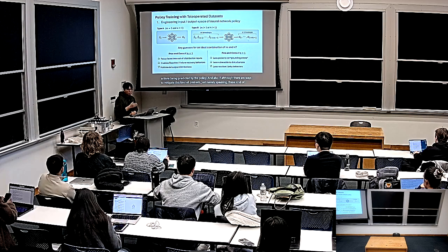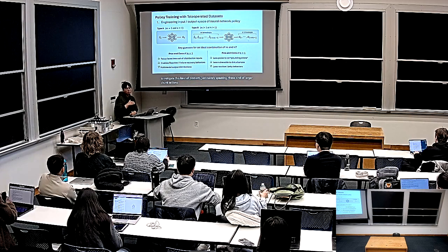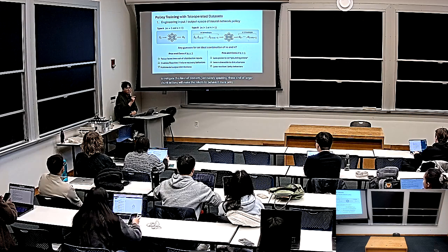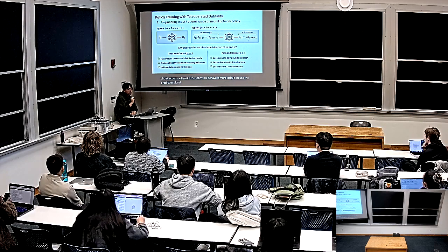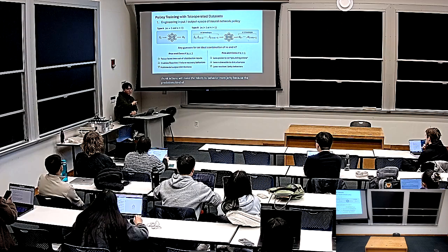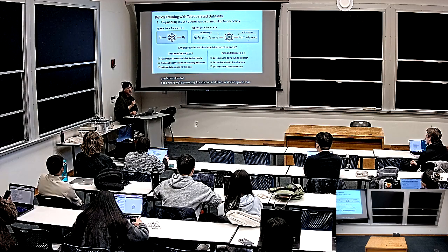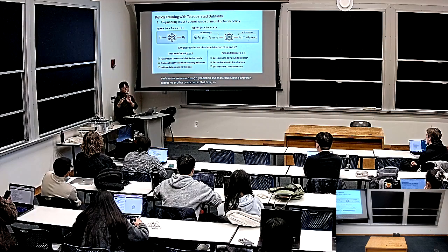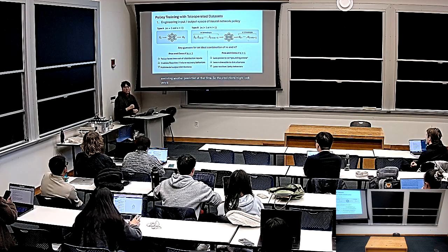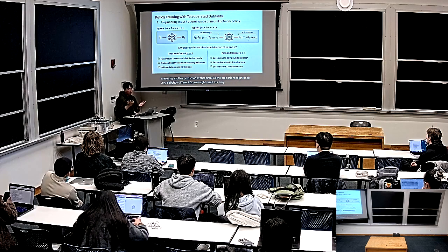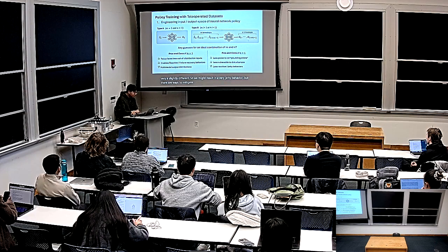And also, although there are ways to mitigate this problem, just naively speaking, these larger action chunks will make the robot behave a bit more jerky. We execute one prediction, then recalculate, and then execute another prediction, so the predictions might look slightly different and we might end up with very jerky behavior. But there are ways to mitigate these problems.